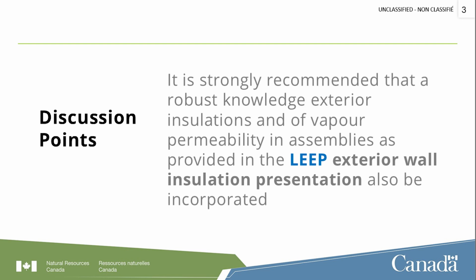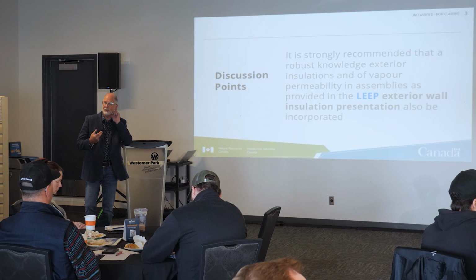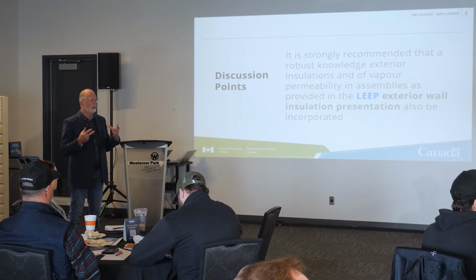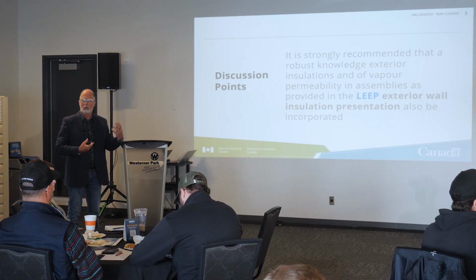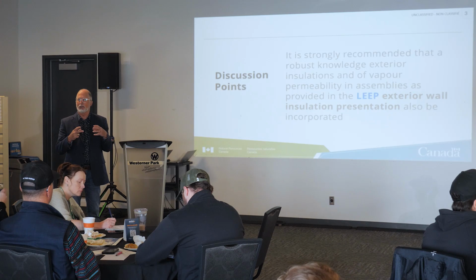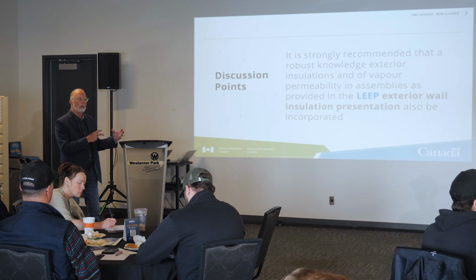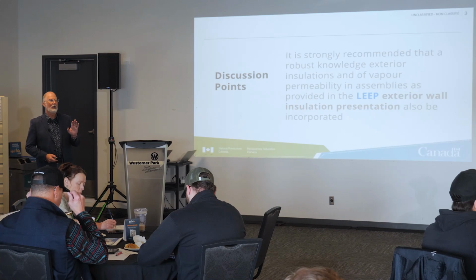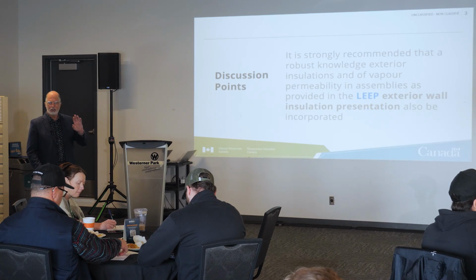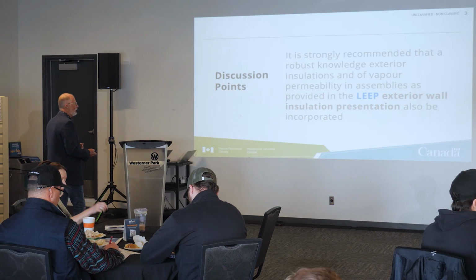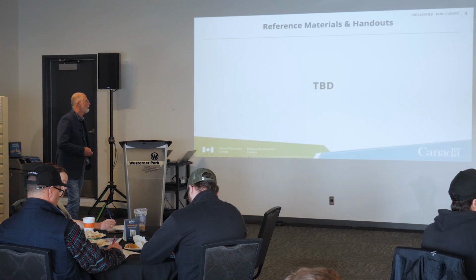One of the things we strongly recommend is, if you haven't seen the LEEP program on exterior wall installations, one of the challenges is when you're trying to integrate a window with putting exterior insulation on, how do you get that integration to work together? The two programs that work really well is the LEEP exterior wall insulation program, because that talks about first and second plane of protection, how to get the insulation in the right location. Does the weather barrier go outside, inside? How does it tie into the window, and all those details? So that's one I'll leave you with.